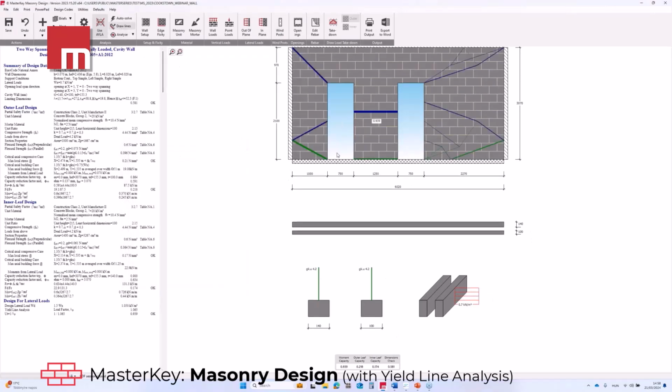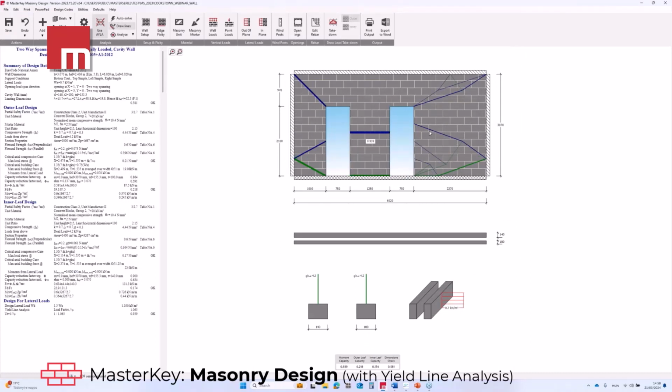The design is ready. So I've used the advanced sheet analysis to calculate this masonry wall. As you can see, it's okay, so it works. However, this is the advanced sheet analysis method inside the MasterSeries masonry module. But as you know, you can use not only the advanced sheet analysis, but you can try out how the design looks using the old-fashioned sub-panel methods as well.